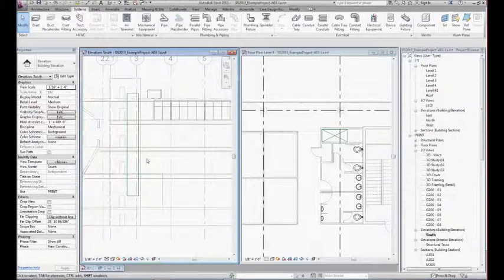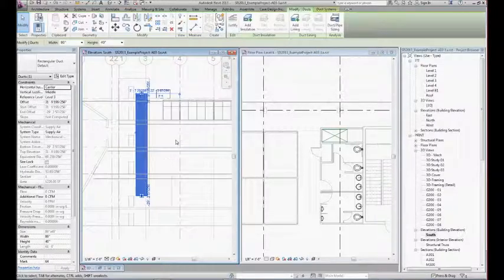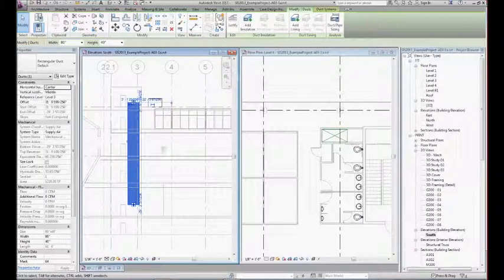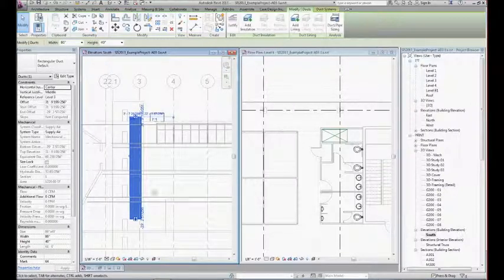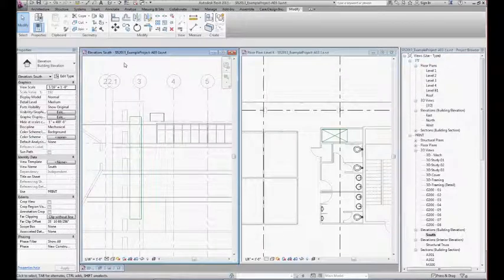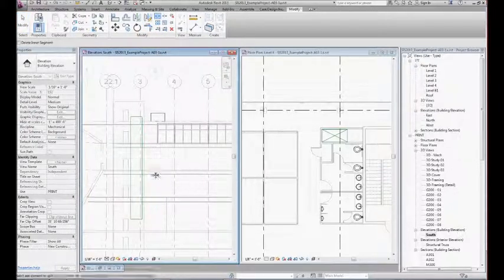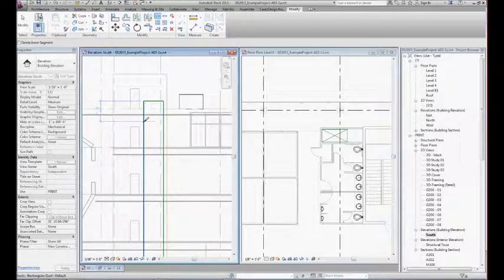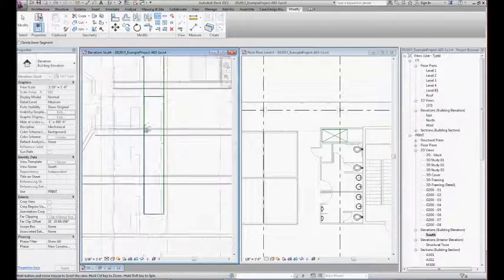And in building riser diagrams, you'll typically see that the duct continues to decrease in shape as it goes down. If you can do that in your building, it's nice. It means you can take up a little less space. So what I can do is go to Modify, and I have my different line tools here, Trim and Split, which is SL. I'm just going to split it and decrease it in size as I go down the building.